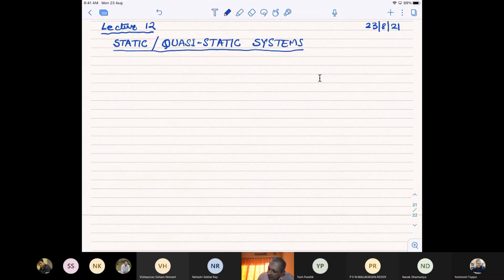And here you have the inertial number. If you remember, it is I, which is defined as the shear rate gamma dot times D divided by the square root of the pressure divided by the particle density. So this is a dimensionless number which says how rapid the flow is.